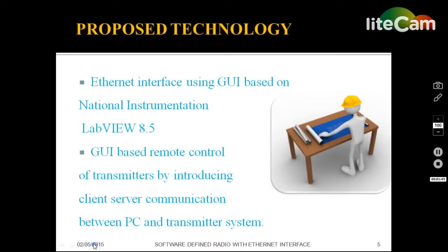There are two radio nodes which are controlled using GUI developed in the LabVIEW. The client part is realized using LabVIEW GUI, which is interfaced with the PIC node using Ethernet cable. Ethernet interface with the PIC is done with the Raspberry Pi board. The two parameters like frequency and power levels of transceivers can be adjusted using this LabVIEW GUI.